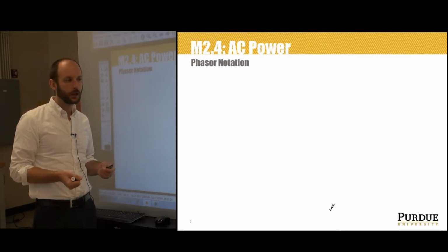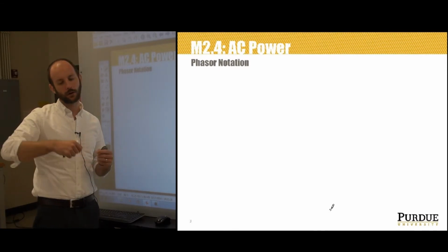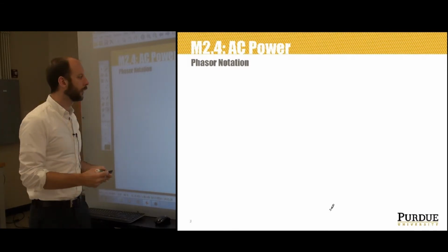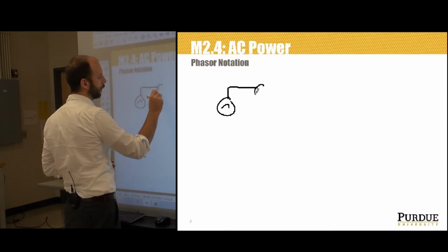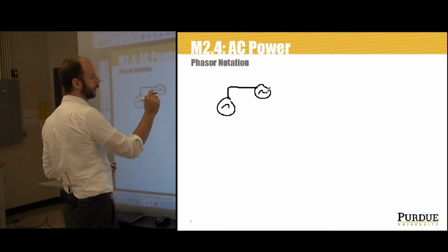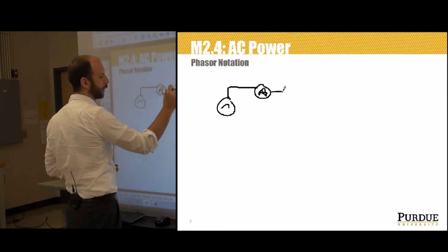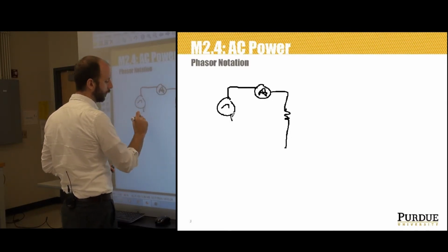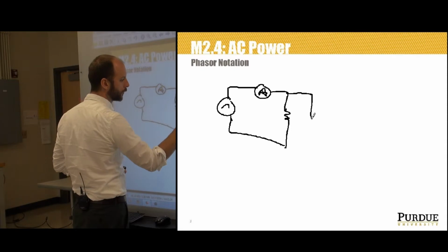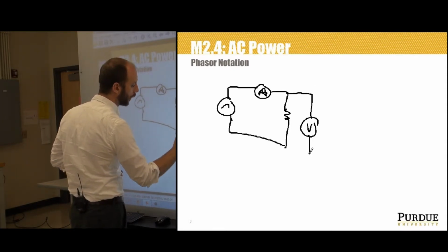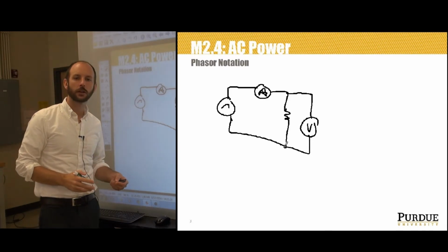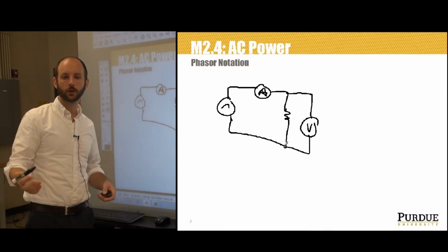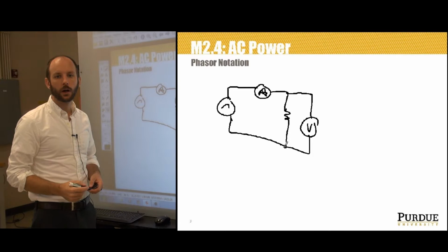And if I interrupt the circuit and measure the current flowing to that light bulb, or measure the voltage across the light bulb, a Fluke type multimeter is going to give me an RMS reading, what we would often call a true RMS reading.